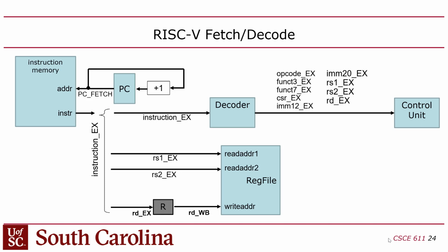Now, why would you do that? Well, it makes it easier to debug, because you don't have to try to figure out what the fields are in ModelSim. In ModelSim, the instruction is just 32 bits. How are you going to figure out where the registers are? I haven't memorized those. I don't know what the RS1 field is in RISC-V. I have to look it up, and if you're trying to do that in ModelSim, it's frustrating. So if you create a decoder, you can just rename through an assignment statement. Well, you have to declare the signal and then assign it.